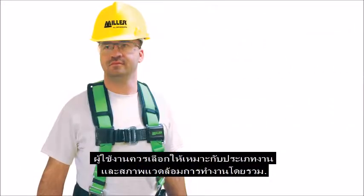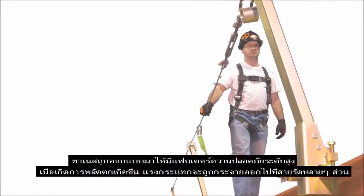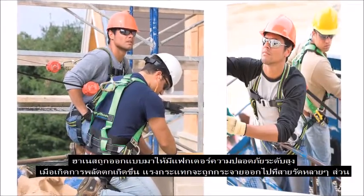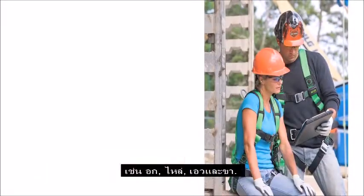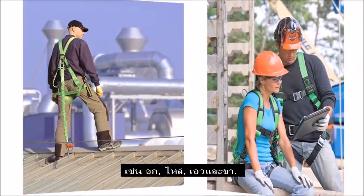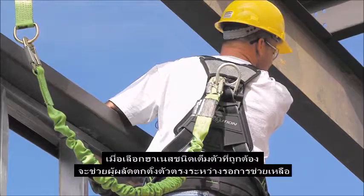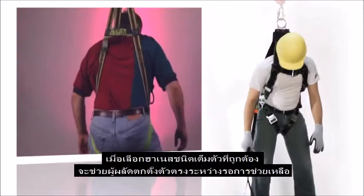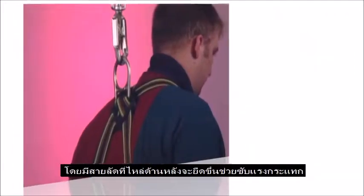The harness style should be selected based on the type of work being performed and the overall work environment. The full body harness offers an inherently high safety factor since fall forces are distributed throughout the body over many webbing components, including chest, shoulder, waist, and legs. In addition to distributing forces throughout the body, a properly fitted full body harness keeps the worker suspended upright while awaiting rescue. This is due to the sliding back D-ring, which slides along the webbing to the back of the neck once a fall occurs.